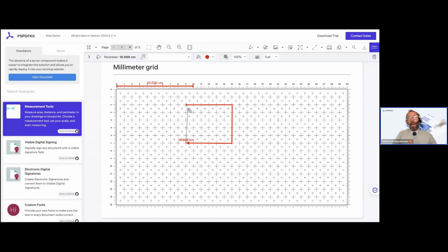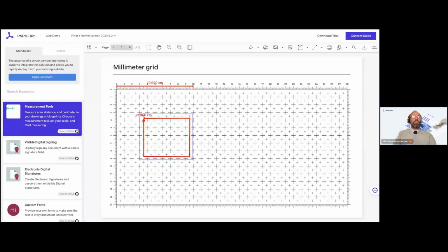You'll see something else as we're getting close to the original point, because this perimeter is typically used for a surrounding. It now basically snaps to the original origin point, which makes it super useful. We just click to finish that off, and then always within the tool is more intuitive. Now we just use escape. So if I hit escape, that exits from the drawing mode, and then now we have our perimeter annotation there.